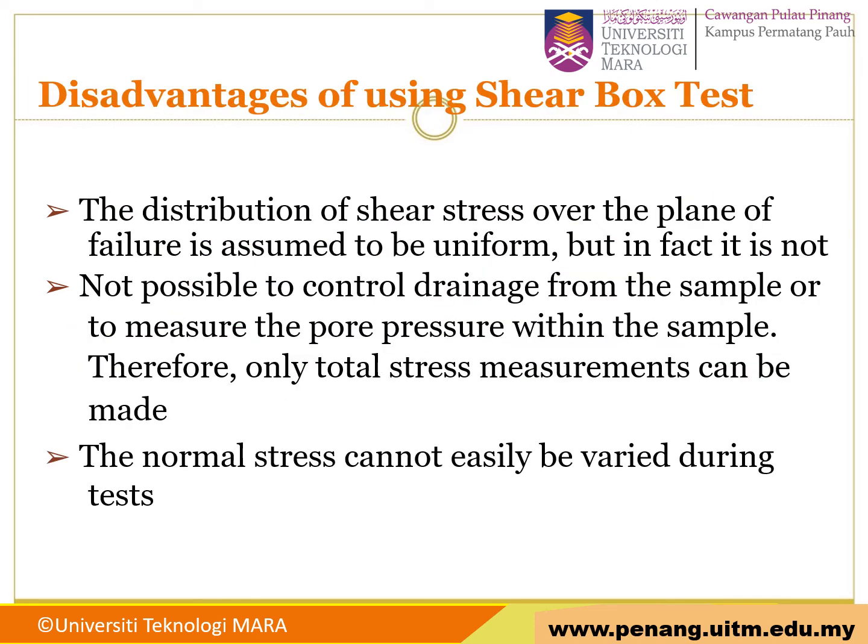Alright guys, however, there are disadvantages of using the shear box test. First, the distribution of shear stress over the plane of failure is assumed to be uniform, but in fact, it is not uniform. So we just assume. Number 2, it is not possible to control drainage from the sample or to measure the pore pressure within the sample. Therefore, we only get the total stress measurement. We cannot get the value of effective stress. Another one is that normal stress cannot easily be varied during the test.